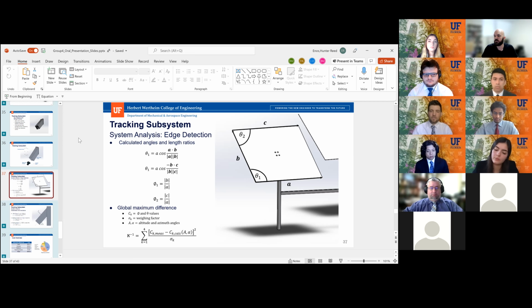So with your 900 watts per module, when you say module, is that a group of 4 or is that each individual one? It's a group of 4. A group of 4. So your area that you're taking up is a 2.1 meter by 2.1 meter field, and you're going to need about 1,200 of these to get your 1 megawatt of energy. It's going to be a pretty wide field that the spacing is going to be taking up, correct?